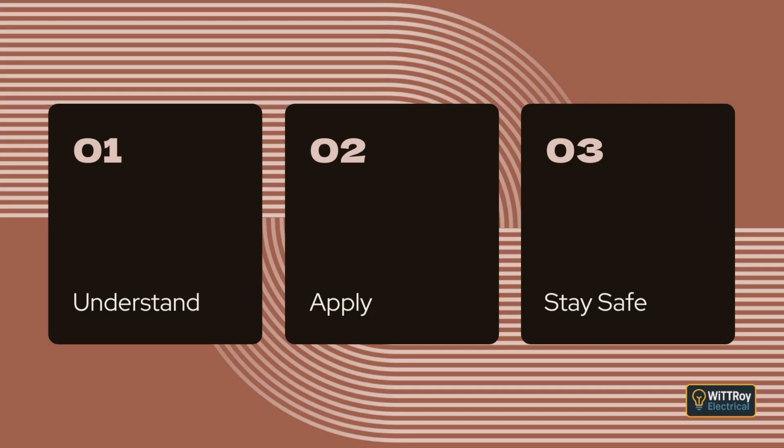Clause 3.10.3.9 Cable trunking. Cable trunking must be installed so that its covers can be opened where practical, and covers must be continuous when passing through walls or floors. The full length of the trunking must remain accessible. Trunking must not rely on removable covers for cable support. Non-hygroscopic trunking must be used when enclosing insulated unsheathed conductors. Any live parts of accessories mounted on trunking must be arranged so that basic protection is provided, consistent with Clause 1.5.4.